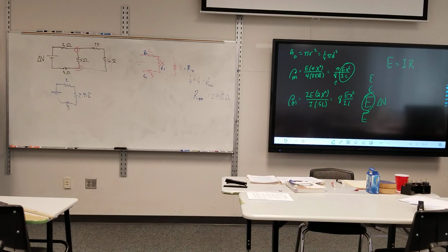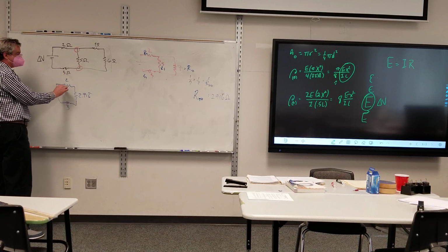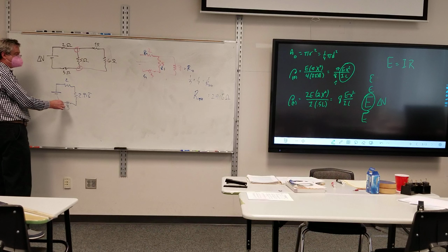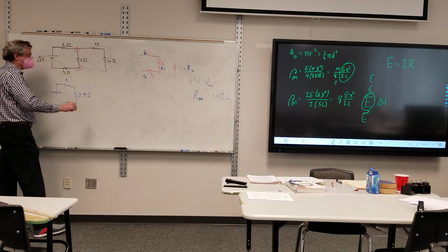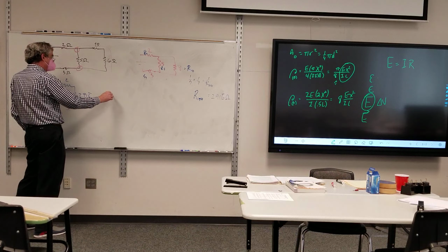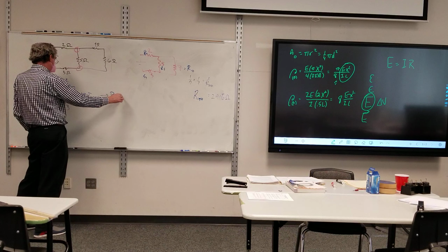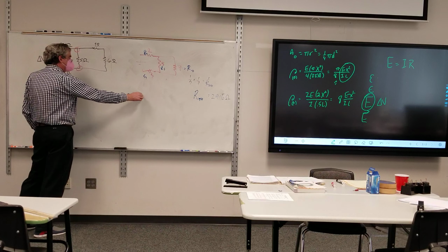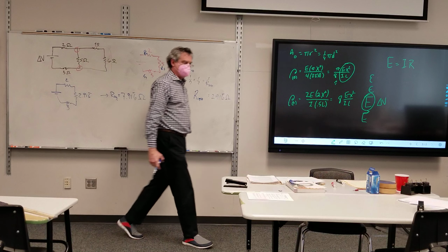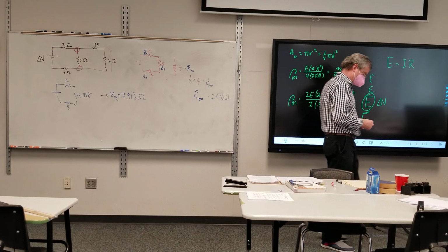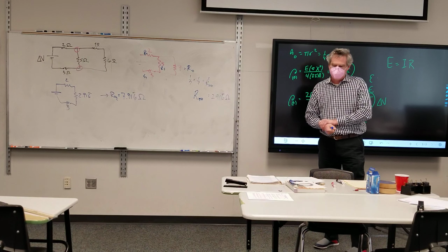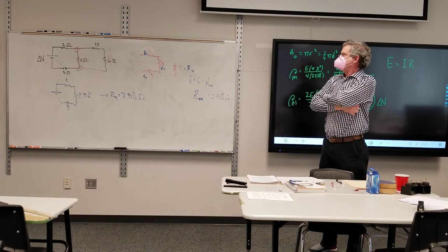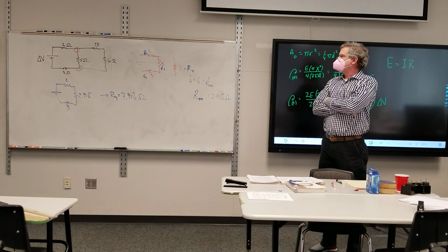Now what? Just add them all together. Yep. That's a series there, because current flowing across the first has to flow across that, has to flow across that. There's no junctions, nothing taking it a different path. So we end up with my equivalent resistance, 7.916 repeating ohms. Nice.